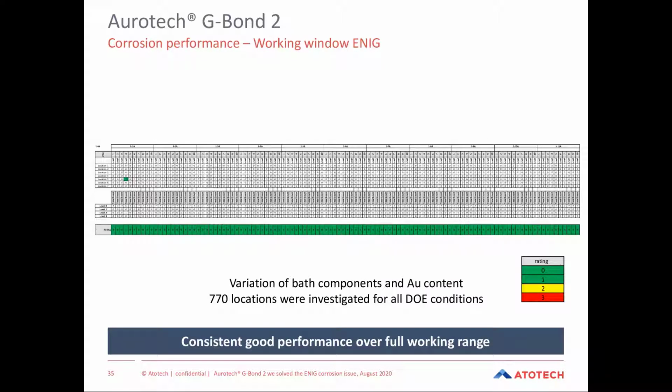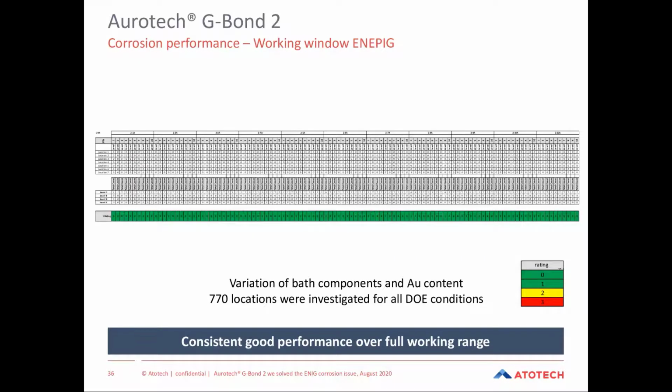So these are the results for ENIG, and for ENEPIG it is actually similar. You again have the 770 locations which were investigated, and 99.5% are totally corrosion free. So even in this working window, where we are far outside of the target values, the bath performs well.